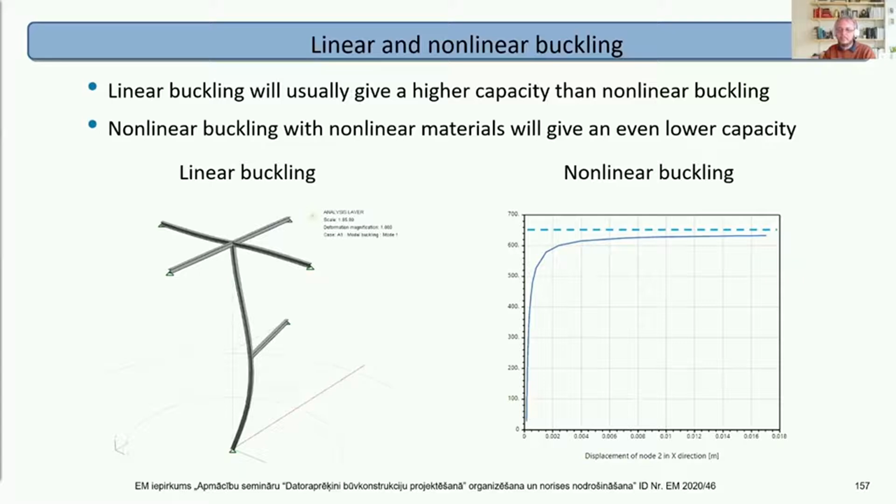Sections start to go, and yes, it is a non-linear relationship once you get into the low buckling values. Obviously, if you've got a buckling value less than 1, it has failed already, and you need to deal with it immediately.